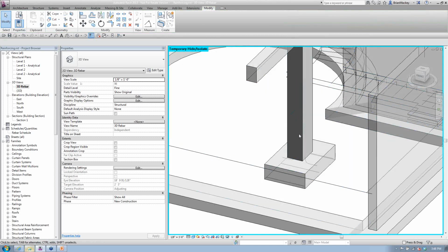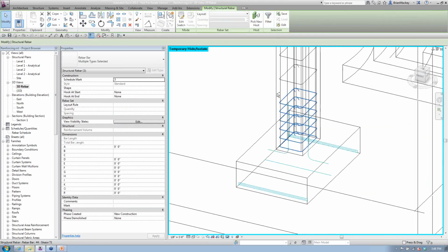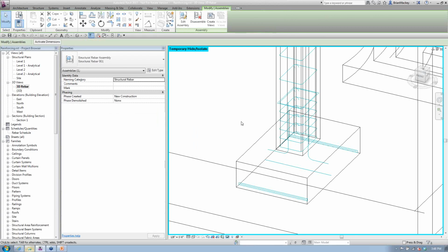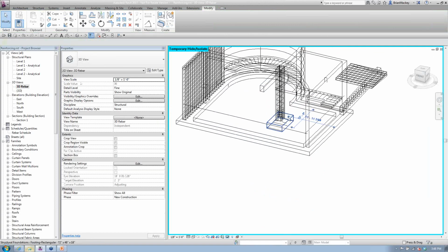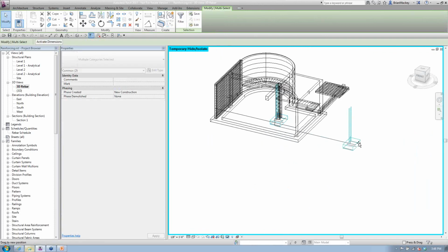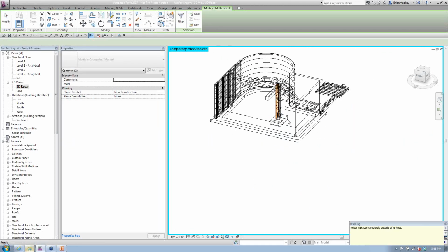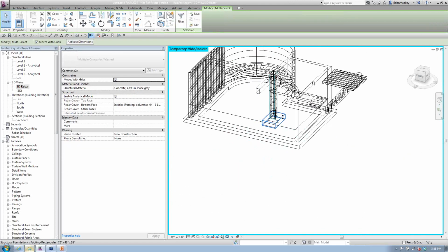So a lot of this stuff, I'm going to go into wireframe again here. I could grab that rebar, this rebar set, this rebar set. I personally like the assembly theories on this one, so I would go create an assembly for this. And I'm just going to let everybody know, because you made the comment, for what you're doing, Greg. Greg designs custom dairy barns and milking facilities for cattle.